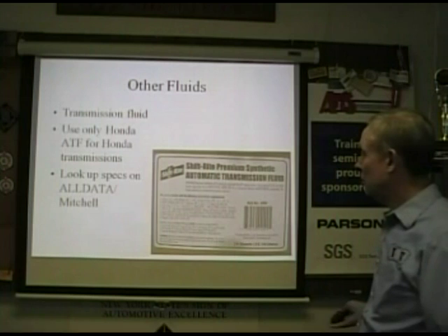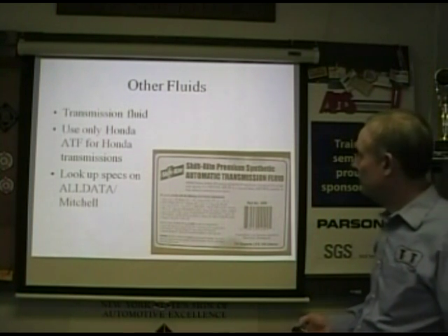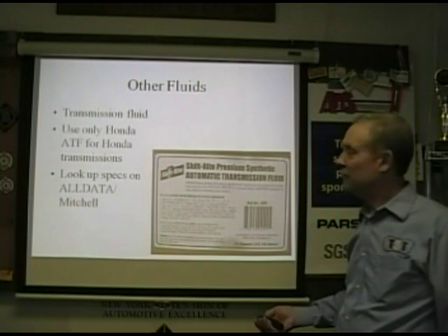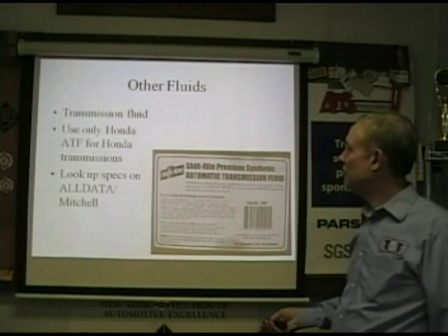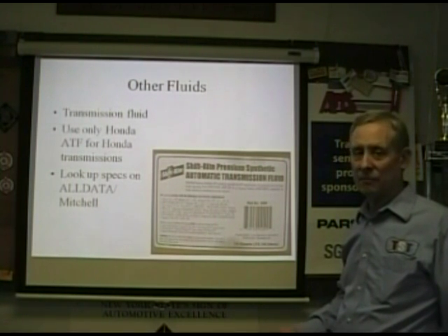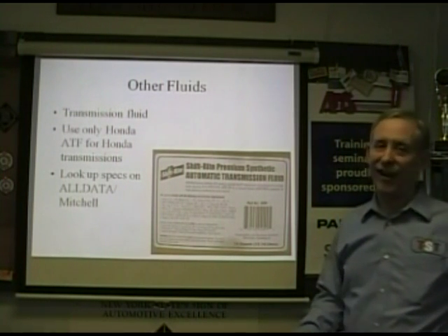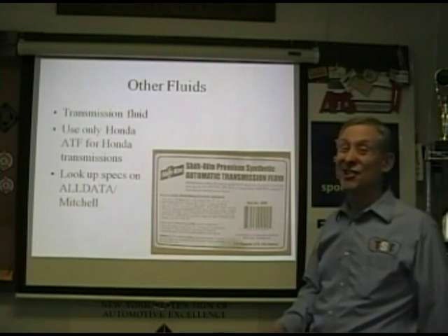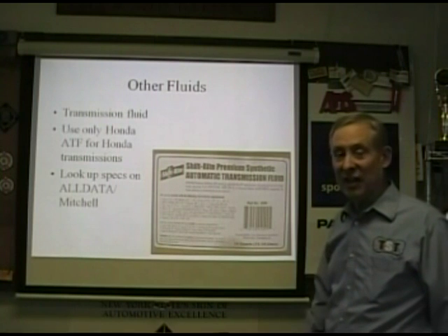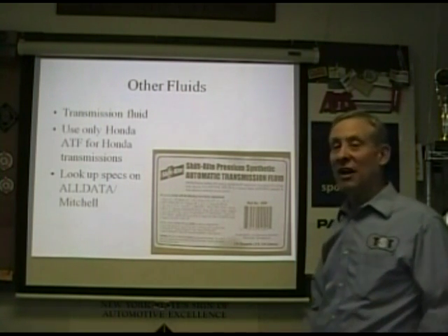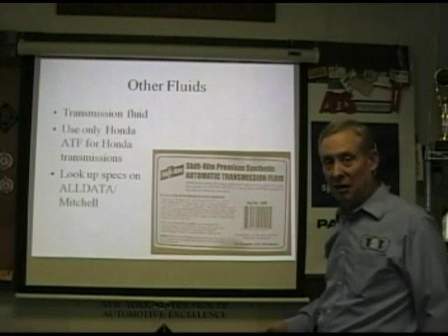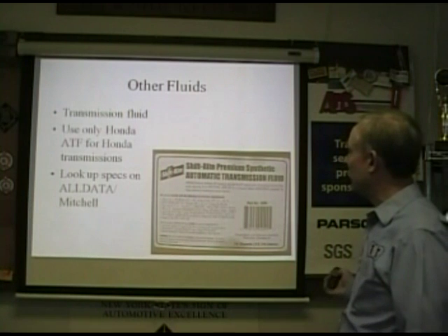Just a note on that Honda: guys that rebuild trannies, some of our members, Mike and Pete and Kevin, they'll tell you that Hondas are real finicky. Even though LubeGuard's a great product, you have to be real careful. You're probably better off using a Honda fluid, or that synthetic that they have, which seems to work okay with the modifier. In my current Volkswagen world, that's true of the DSG transmissions as well. Those babies are picky, and we've been changing valve bodies, so you don't want to play with it. You've got to put the VW fluid in that case.